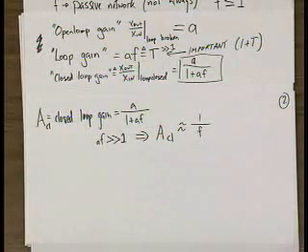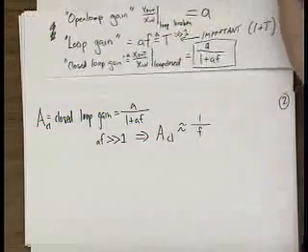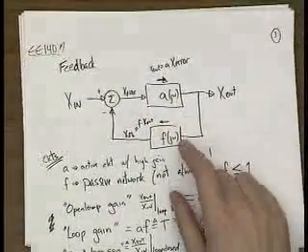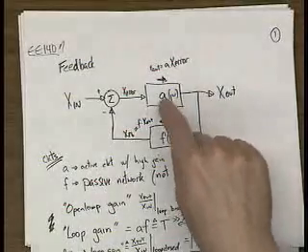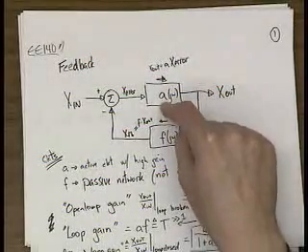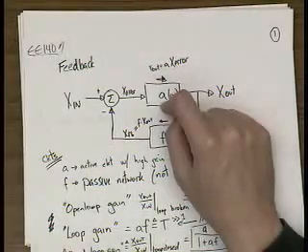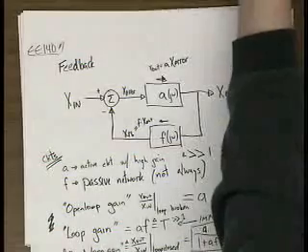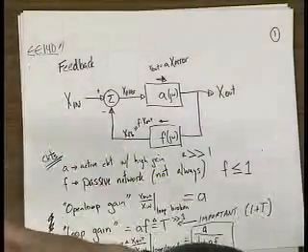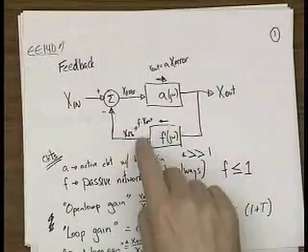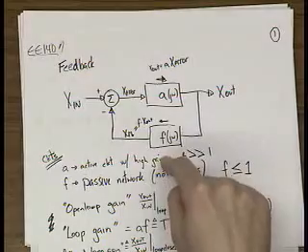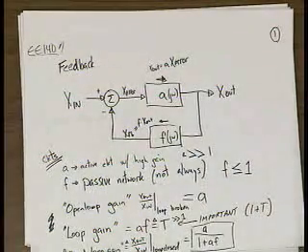what this means is that the overall behavior of the circuit, and the primary reason we use feedback, is that if you look at this network, and we'll get into why later, this active circuit with gain A much greater than 1, its gain isn't going to be very well determined. Over frequency, over process variation, over voltage supply. You probably saw some of that in Project 2. Your gain kind of changes. You change an input common mode, the gain changes. But this feedback network can typically be set by a ratio of passive devices, like a ratio of resistors. Those ratios can be very well controlled.